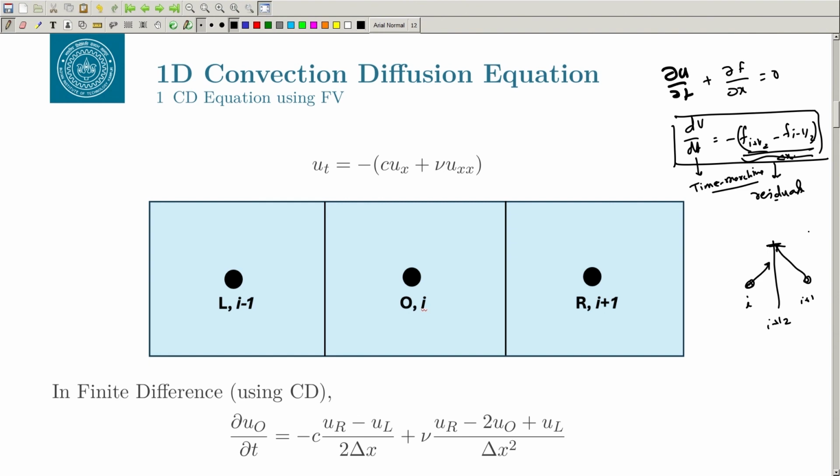So, that is where the flux schemes come in, whether you use the Lax-Friedrichs scheme or the Roe scheme or the van Leer scheme or any scheme like HLLC, AUSM. What they do is take the reconstructed values from the left and right across any cell and give you the unique flux. There are certain properties on how the flux should be so that the code does not diverge, and good flux schemes retain those properties. Of course, while trying to do that, you may also have some dissipation in the scheme.